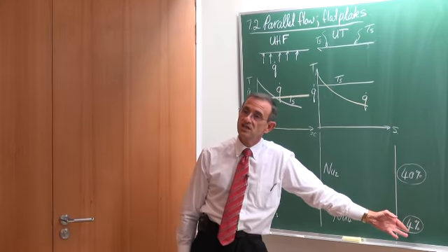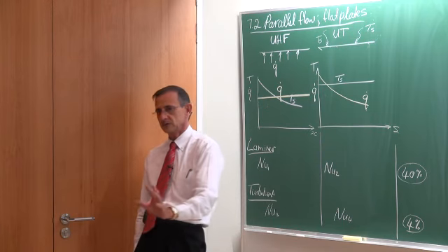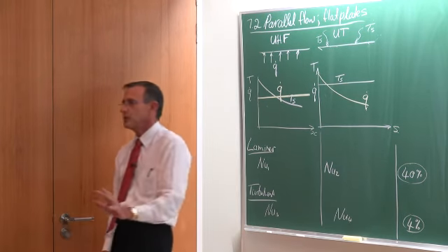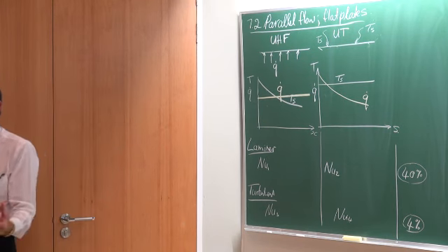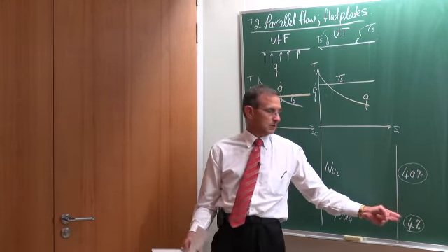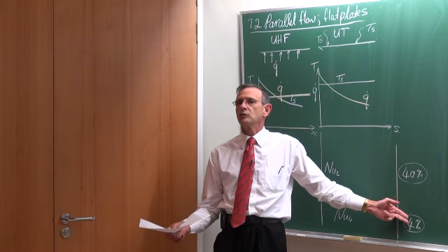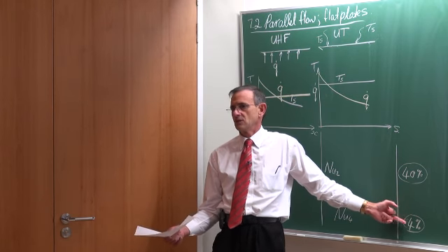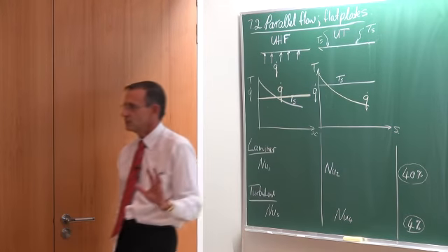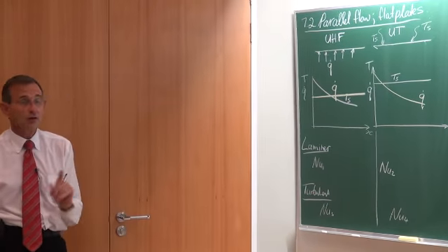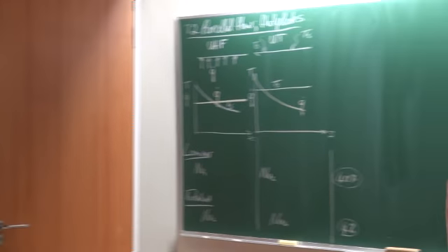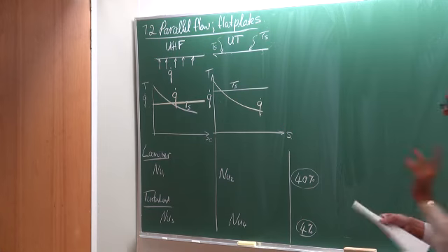For this reason, you will see that when the flow is turbulent, people will not even normally say whether it is for a constant wall temperature or a constant heat flux, because it really doesn't matter. Most correlations in literature, if they are good, give heat transfer coefficients to within plus or minus 20%. So they are not that accurate in any case, and a 4% difference is not going to be a big deal. But in the laminar flow regime, it is very, very important, and we will see applications of that also in the next chapter.